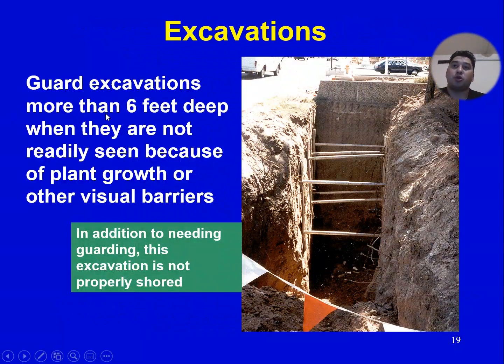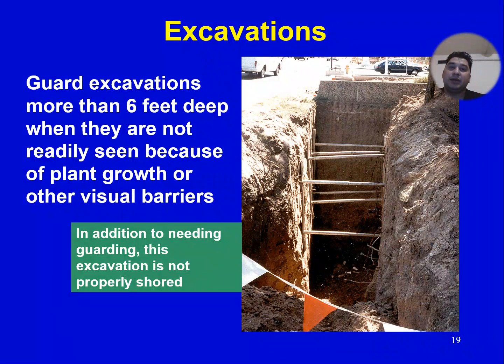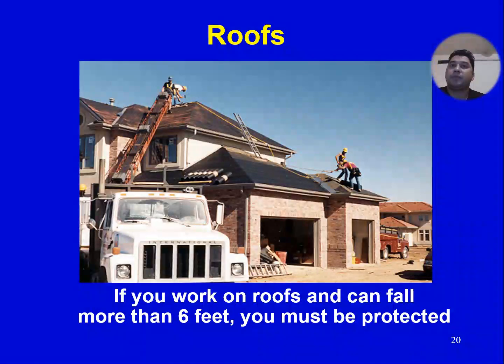Excavation. Guard excavations more than 6 feet deep when they are not readily seen because of plant growth or other visual barriers. In addition to needing guarding, this excavation is not properly shown. You can see here this excavation is not properly covered or guarded, so it is not suitable to work near. That's why all excavations should be properly guarded and covered, or we need to make sure that a fall protection system is used.